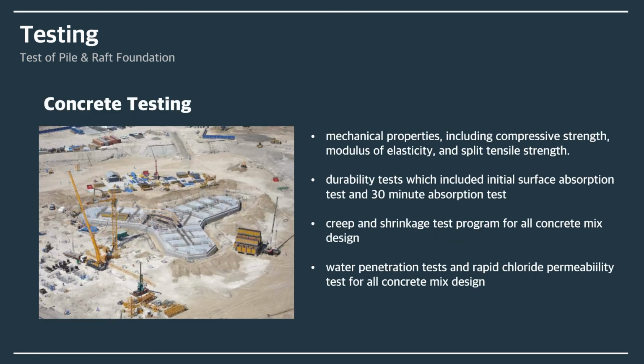In this slide, concrete testing. For concrete testing, there are many testing programs for all concrete types needed for the project. For example, mechanical properties, including compressive strength, modulus of elasticity, and split tensile strength, and durability tests, and creep and shrinkage tests, and water penetration and permeability tests for all concrete mix designs.